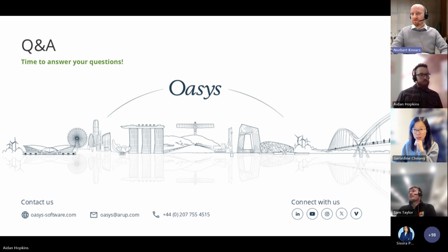So the next question, with regard to use of stages for tunnel construction to pick up intermediate cases which are more critical than the end case. How do you typically show this on ground movement contours? Is it possible to produce ground movement contours that show an aggregate worst case ground movement for each point from all stages?